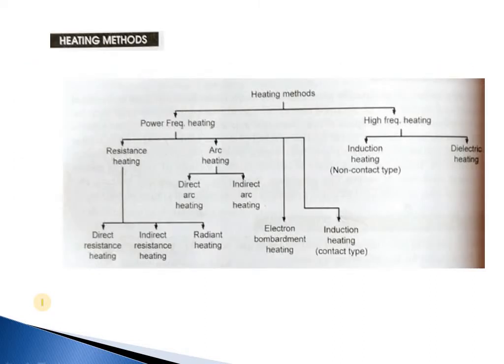Now, heating methods. There are several methods for heating purposes also. Firstly, it is divided into two types, that is power frequency heating and high frequency heating. Power frequency heating is again divided into two parts, that is resistance heating and arc heating.